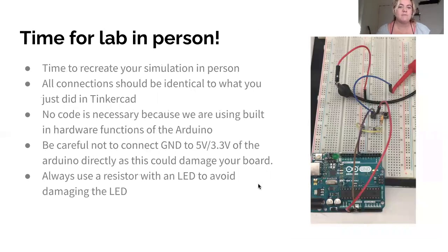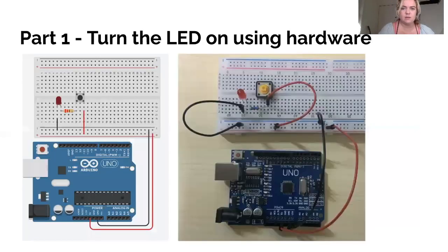It is time for the lab in person. You can recreate the simulation in person, and all connections should be identical to what you just did in Tinkercad, and no code is necessary because we're using the built-in hardware functions of the Arduino for this one. Be careful not to connect ground to 5 volts directly because this could damage your board, and always use a resistor with an LED to avoid damaging the LED.